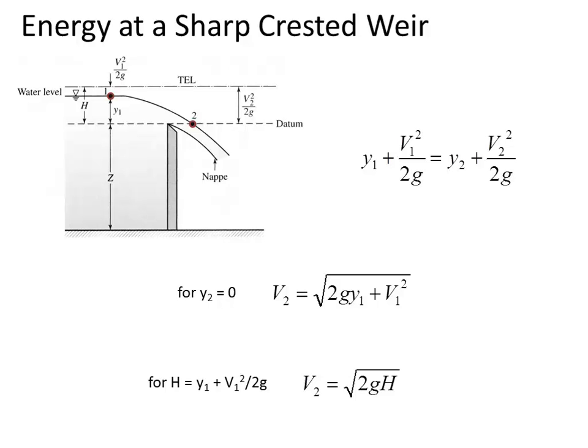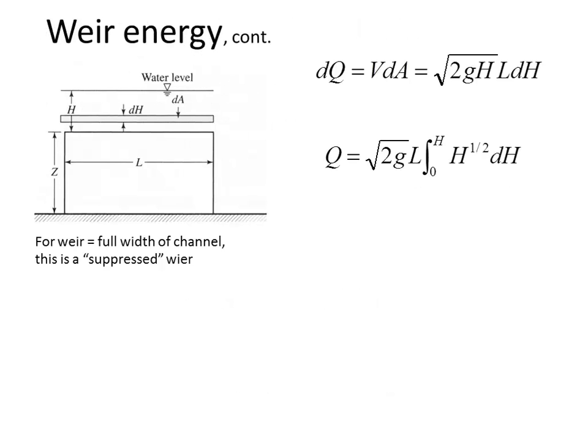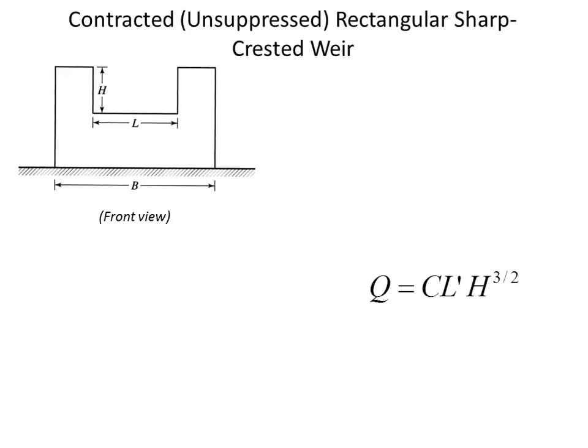And so sometimes one of the effects that goes into the coefficient of discharge that's used for sharp-crested weirs is a vacuum underneath the nappe that's artificially pulling it down, where if you vent in there, it would cause the nappe to raise a little bit because there isn't a negative gas pressure underneath the nappe. That's one of the reasons that these contracted weirs are sometimes used: when you've got it contracted like that, then that does allow for positive ventilation underneath the nappe.